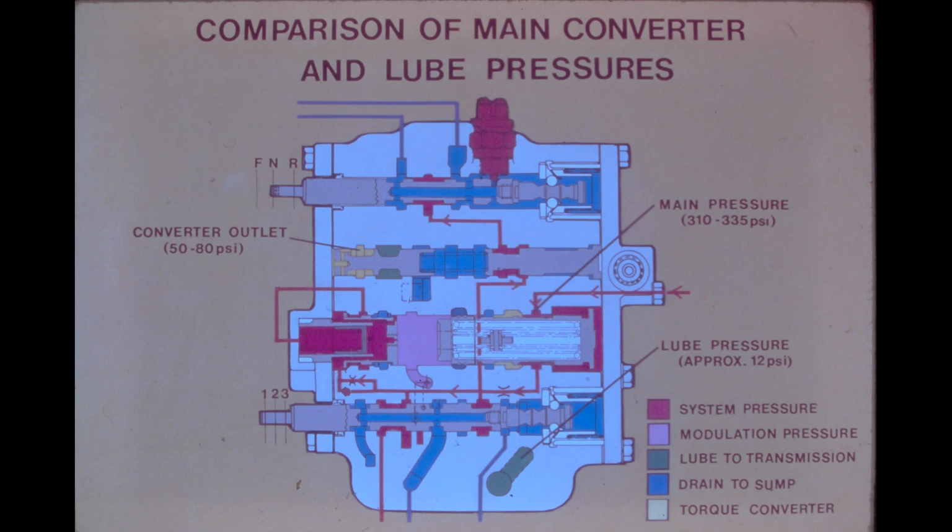Low main pressure could be caused by a clogged suction filter, an inefficient charging pump, a weak 30 psi spring on the outside diameter of the regulator spool, a weak modulator spring, or a spool that is bound open, indexing a large quantity of charging oil to the sump. Excessive leakage at the dump spool or the modulator piston would also produce a low main pressure reading. Pump efficiency can be checked with a flow meter.